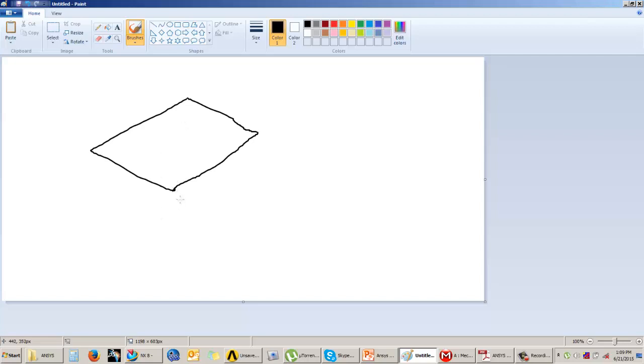Now, how do you check the warping factor? What we will do is assume that there is a diagonal drawn in the quad element. So this becomes one triangular element and this becomes the other triangular element. And then we will draw two normals from the triangular elements, and whatever is the angular deviation is reported as the warping angle or the warping factor.